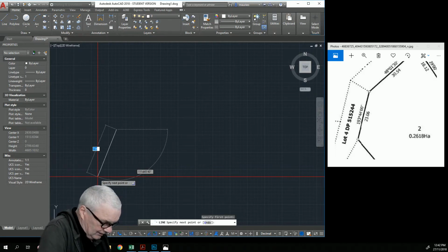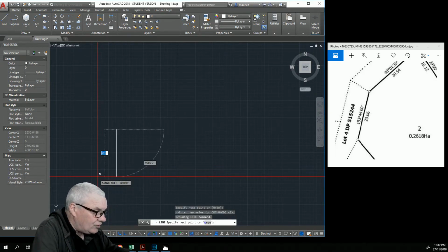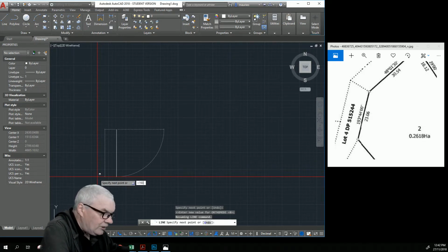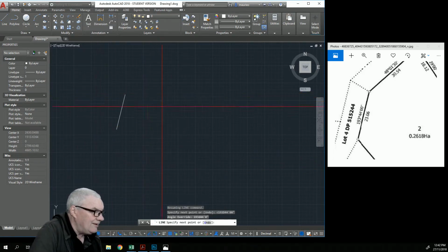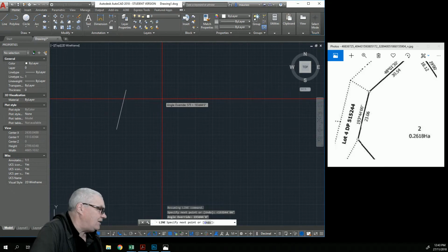So we press shift and the chevron, and then 193 degrees 44 minutes and 00 seconds. I'll put that in. You'll see there the little tab, angle override, 193.44. So that's good.